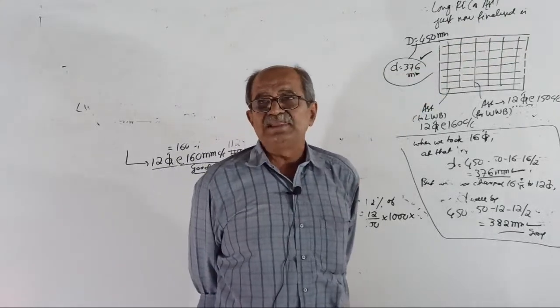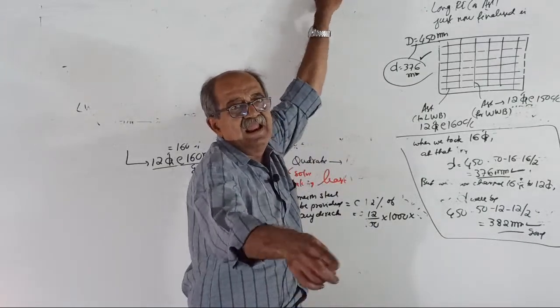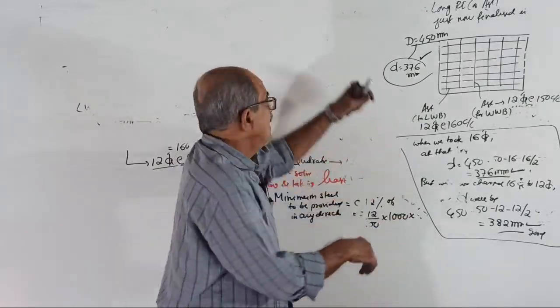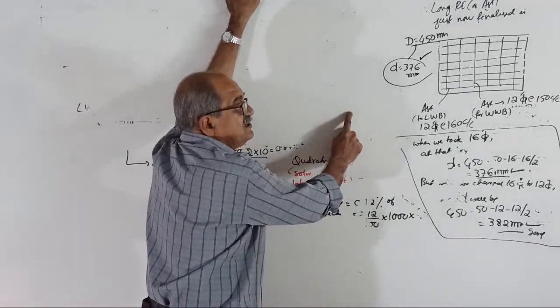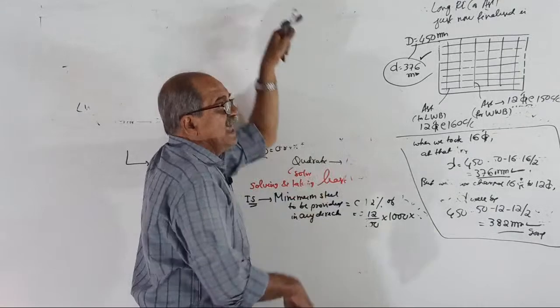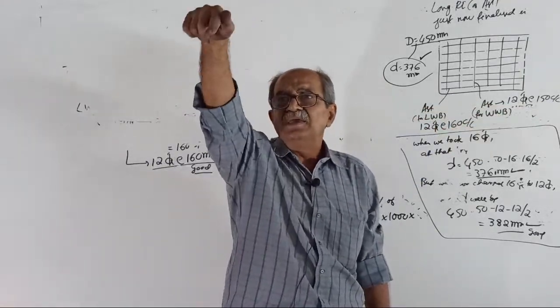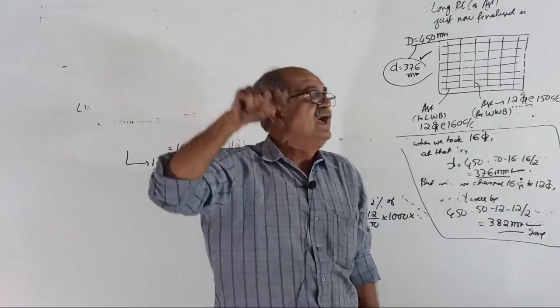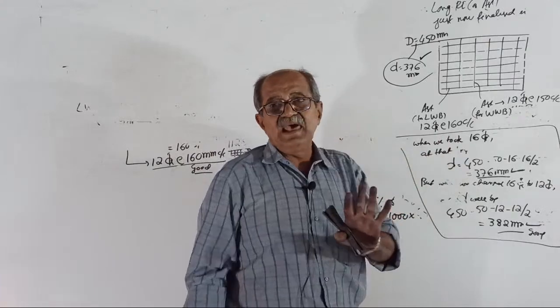When I design the slab by ETABS and SAFE, I will be sitting somewhere there, not near the board. I will move the cursor and tell, see, this steel is 10 tor at 200. Now, tell me deflection, safe or not. You should open the Excel sheet I told you earlier and tell me safe or not. In the same way, an Excel sheet is required.